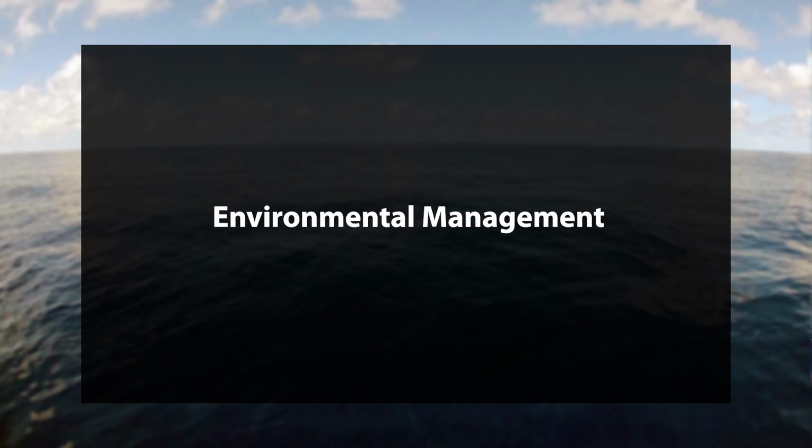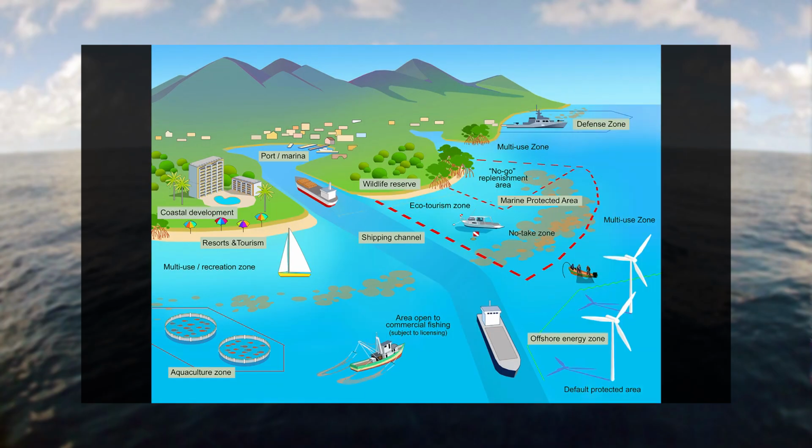Environmental management. Bathymetric mapping serves as a crucial tool in environmental management and marine spatial planning. Detailed bathymetric surveys establish a geospatial baseline of seafloor morphology and habitat distribution. Repeated surveys facilitate the detection of alterations caused by activities such as dredging, trawling, or the placement of infrastructure, allowing for measurement of erosion, sediment deposition, and habitat loss.